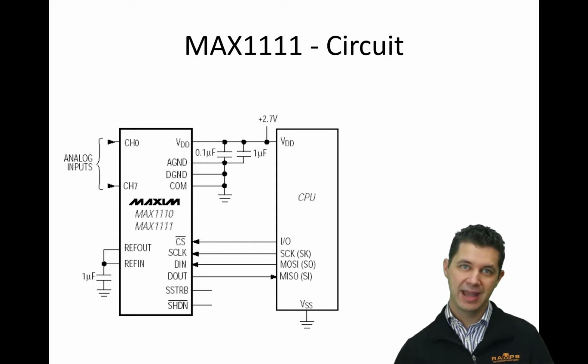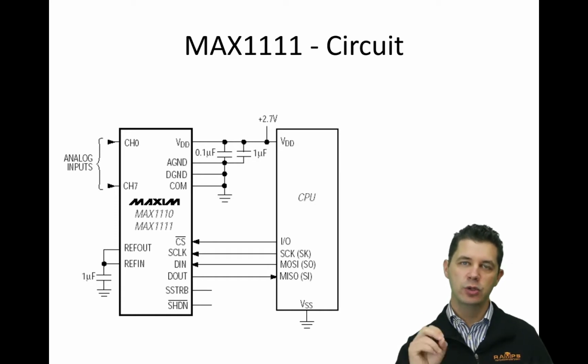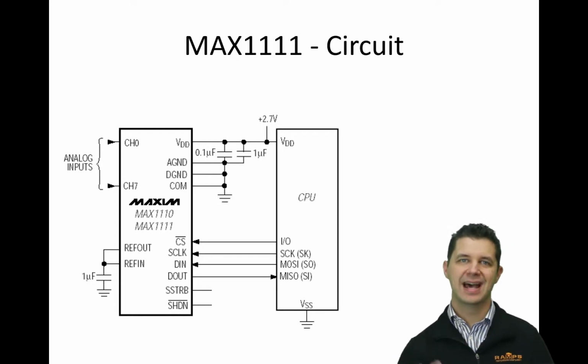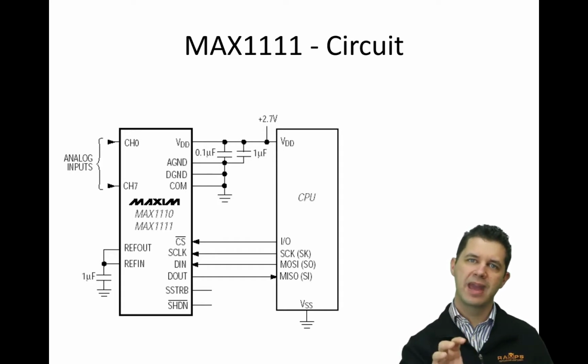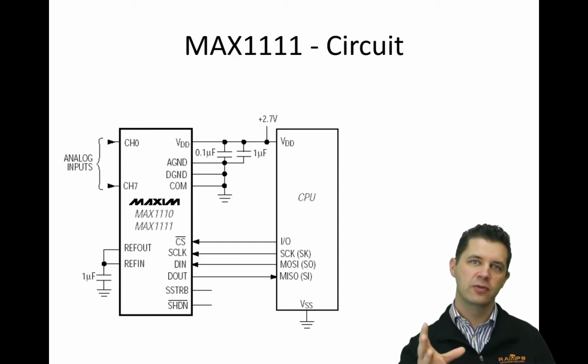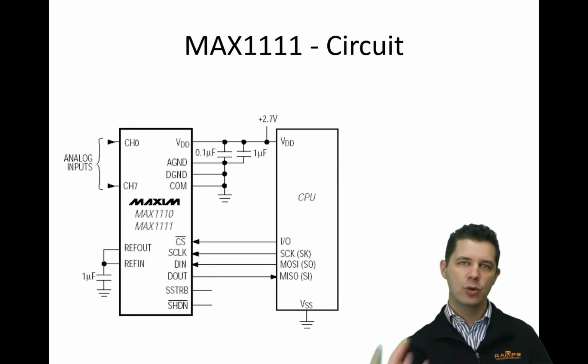One of the things about SPI is it's a bus configuration, so we can have multiple devices all connected to the same pins, each with a different chip select, which we use to choose each one. So this gives you the background knowledge now to actually configure something like this, connect our microcontroller up to our ADC, an external ADC, and get data off it. Now, I'm not going through all the code because we haven't actually covered SPI in detail yet. But essentially, we've got a series of commands that we use from our microcontroller. We send commands to this ADC and say, perform conversion on this particular pin, and it will give us back our data.